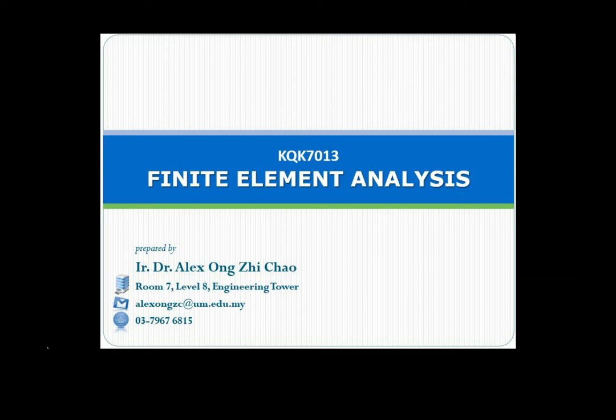We have learned in two-dimensional elements, we have these triangular types, linear and quadrilateral types, linear and quadratics. Then in terms of 3D, we have tetra, hexa, both linear and quadratic types of elements, right?